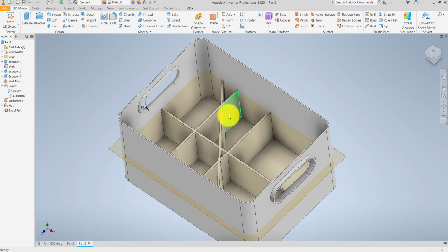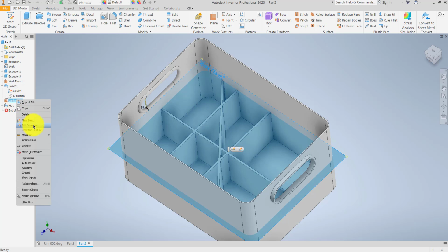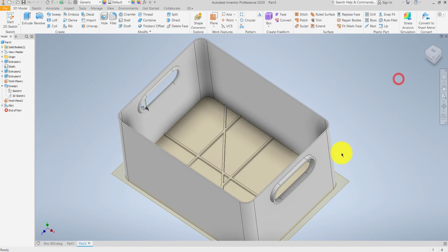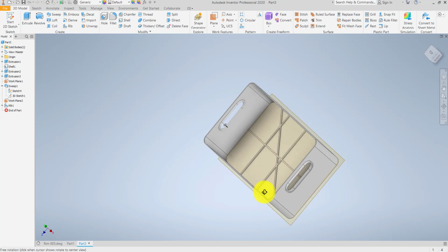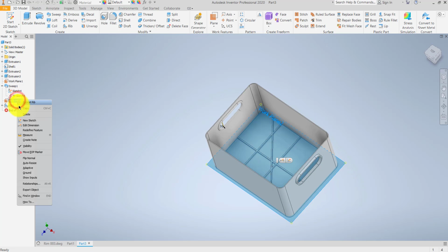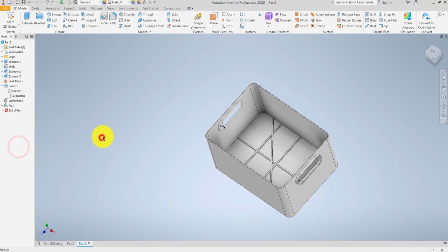Now of course, remember, we don't want this to be really big, long, tall. So if we modify the height of this plane, that will do the job. So right click, and then what? Edit the dimension. It was 100. Maybe I want this to be 5. Nice, job done. That's very good. And of course, I could right click on this plane and say make this invisible.